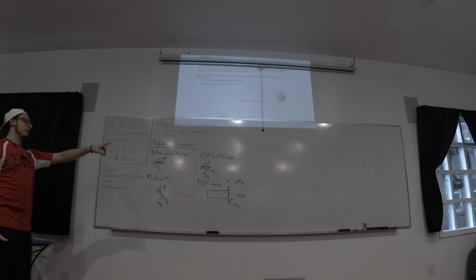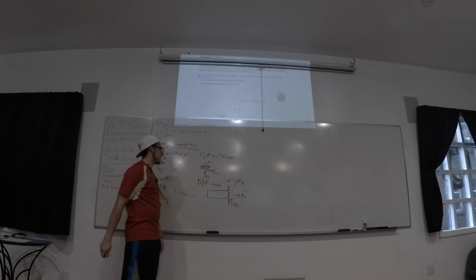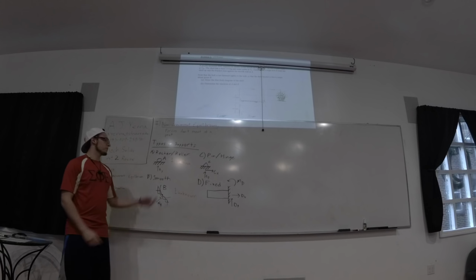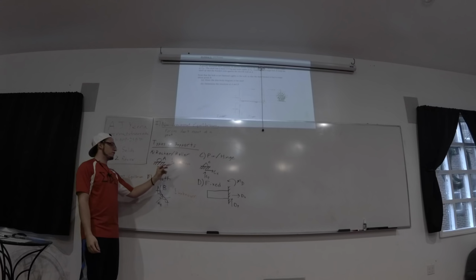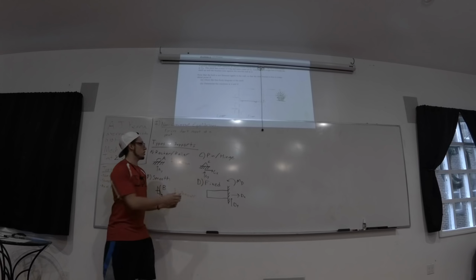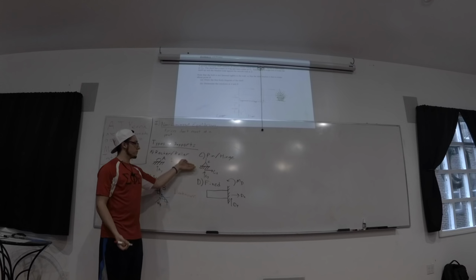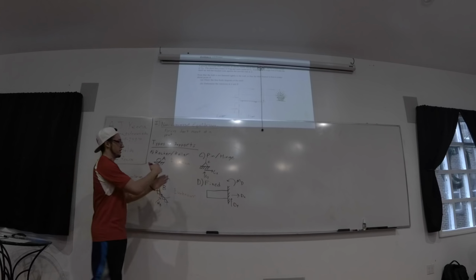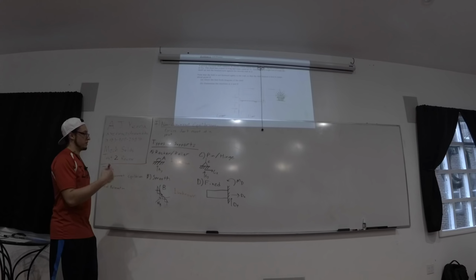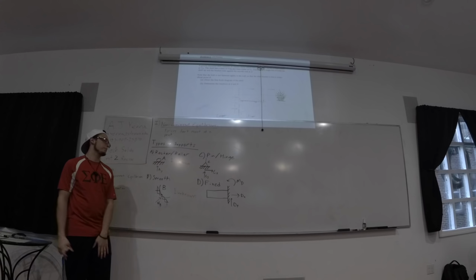The third type is the pin or hinge. The symbol for this one is the triangle with these little fixed hash lines. This one is going to have 2 reactions coming off of it. If the beam itself is going this way, you have one going along it, and then one perpendicular to it, X and Y respectively, depending on how it's drawn. If the triangle's sideways, it'll be different. And remember, when you're taking calculations, you're taking it not from the skewed-off point that I drew. That's just to make it easier. You're taking it from that center point C that you're working at.